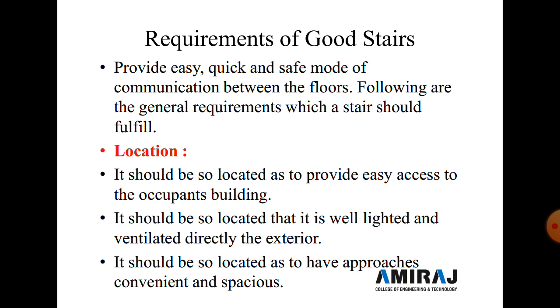Now it should be located so that it is well lit and ventilated directly from the exterior. Generally we locate or fix the stair at the external wall, so from the external window we get light and air.